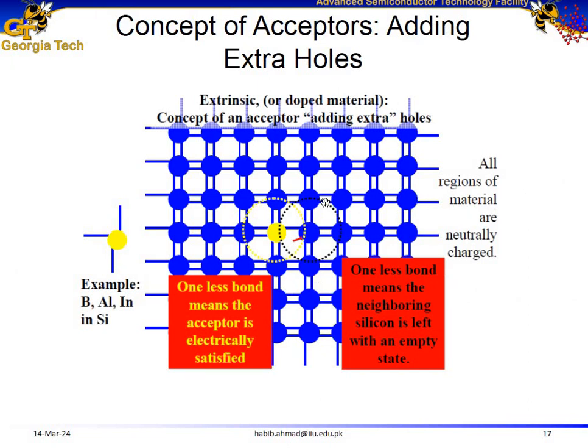Similarly, for p-type doping of silicon, we need boron or trivalent impurity, for example, boron, aluminum, indium, etc. Boron is the most common p-type dopant in silicon. It has 3 electrons in its outermost shell. These 3 electrons make bonds with the neighboring silicon atoms. But then over here, we actually have a missing link. We have an absence of electron. And we know in semiconductors that an absence of electrons is called a hole. So basically, by p-type doping, we actually introduce holes into the semiconductor.